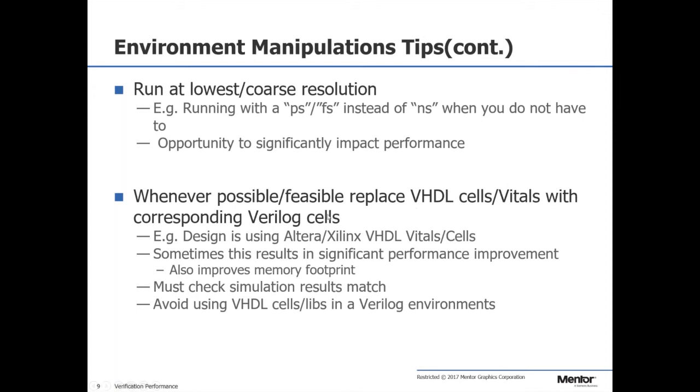So VHDL gate level models, the designers of that spec did not take performance into account, and VHDL VITAL gate level simulations are slow. That is true across Mentor, Synopsys, Cadence, whoever. So if possible, you can still use your VHDL test bench, but generate a gate level Verilog model and just run mixed language with your VHDL test bench and your Verilog gate.